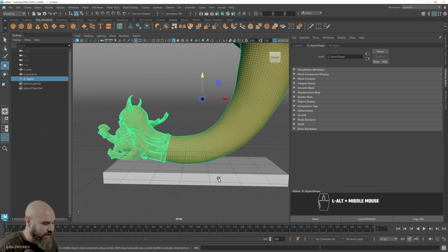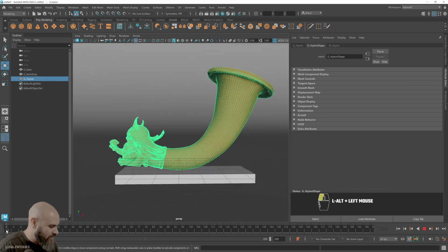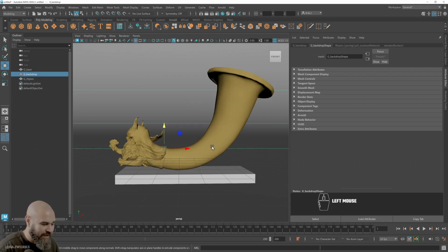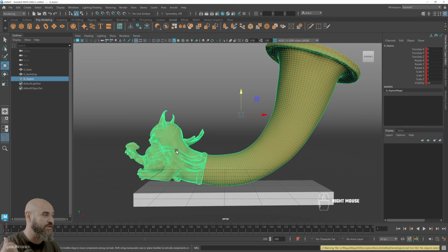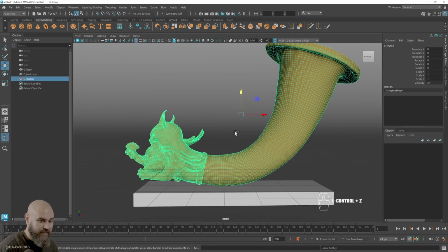So to set a keyframe in Maya is the S key. If we wanted to animate this, the fastest, easiest method of doing it is just hit the S key while it's selected. And you can see here right behind my head that there's this red notch that shows up when you set a keyframe. Also, you'll see I just keyframed every attribute, translation, rotation, scale, by clicking the S key. That's what it does. So if I undo that,